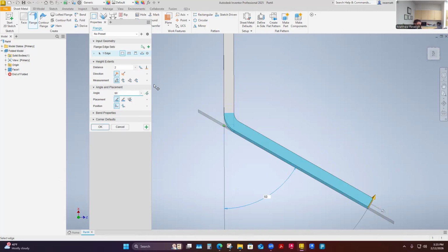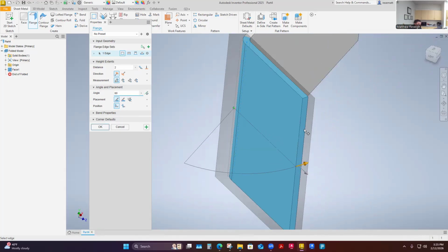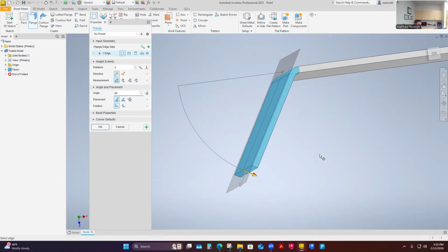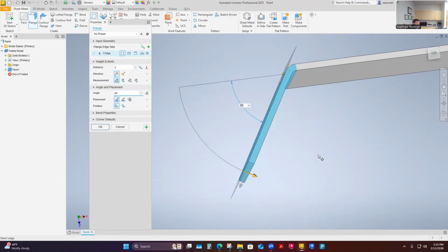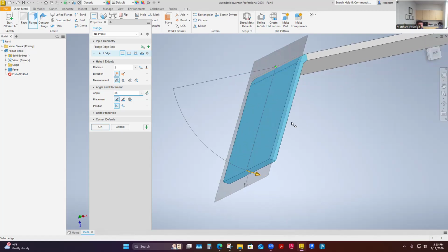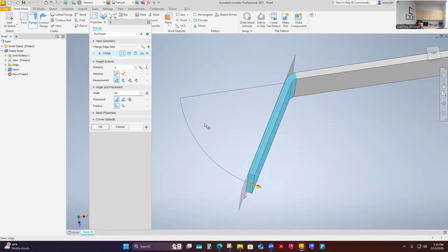So he doesn't bend a full 90 degrees. So that's a 60-degree bend. It shows this reference plane that it's bending. And there's my reference dimension from straight 180 degrees, 60 degrees right there. So you have to know, every angle matters, like where I'm pulling from and where I'm going to. Do I call this 60? Do I call this 30 off of 90? I don't know. It matters, but I have to be aware of at least how the program is pulling that dimension.